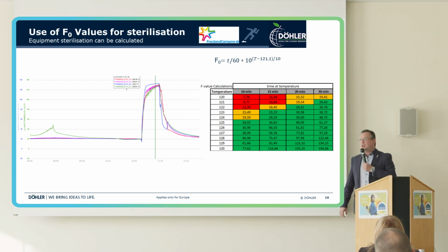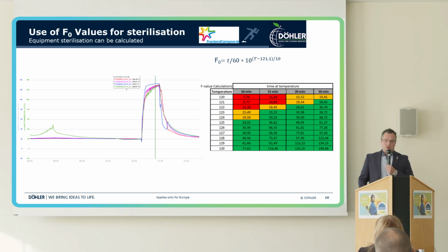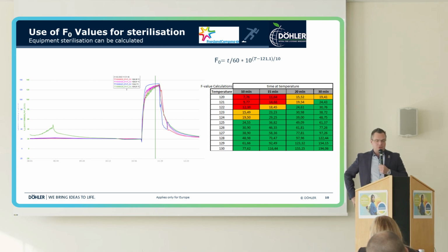Which means if the production line is programmed to count the amount of F values the sterilization process is undergoing, it could be that after approximately 67 to 70% of the sterilization time, you already have reached the amount of F values that you want to have, and basically the production line could have started to cool down at this point already. Meaning you're basically steaming 10 minutes extra, using energy 10 minutes extra, well, you don't have to for your microbiological safety. All wasted energy.